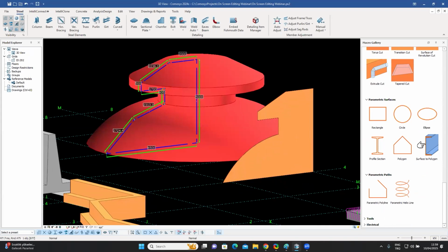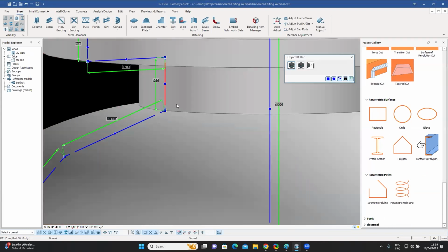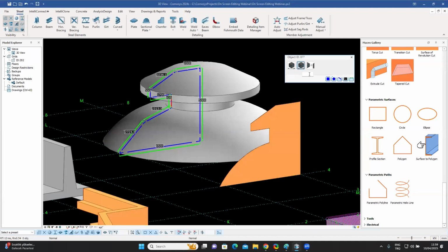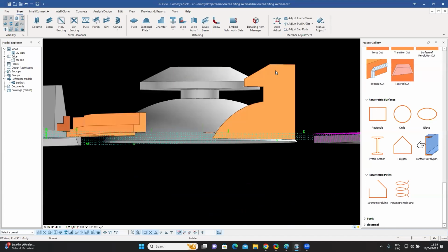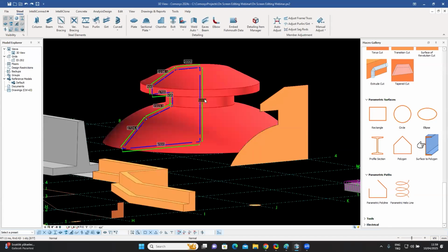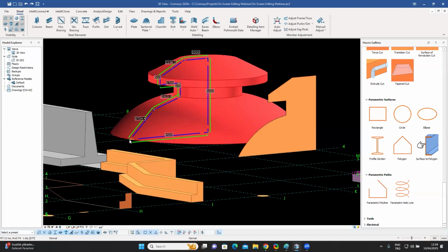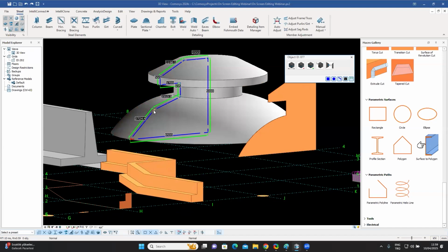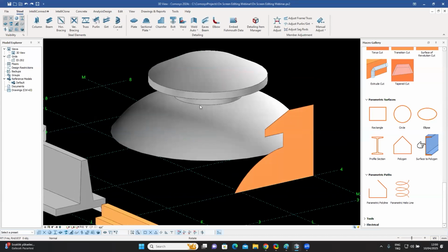If I select this little edge over there and move it, say -500, you see that the neck is becoming thinner over there. So very easily, I can modify the shape, because the moment I select it, all the corner points are at my disposal. I can move the corner points. I can move this point to some other location. I can give a different radius to this chamfer point, etc. So very conveniently, I can create my extrusions and my surfaces of revolution.